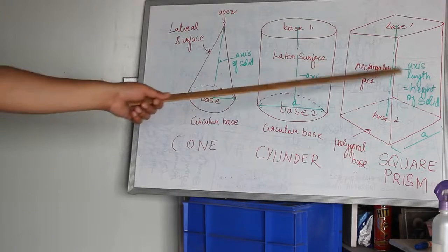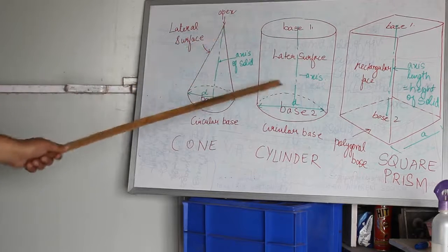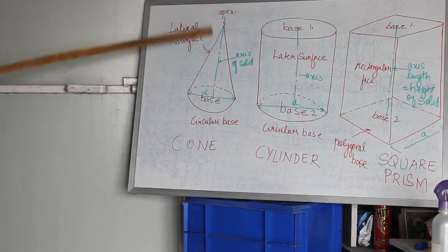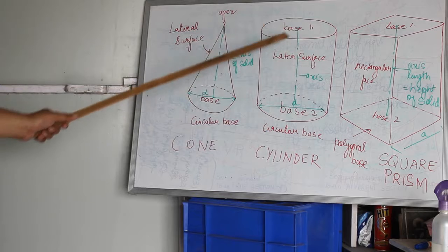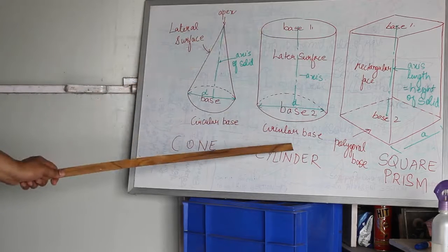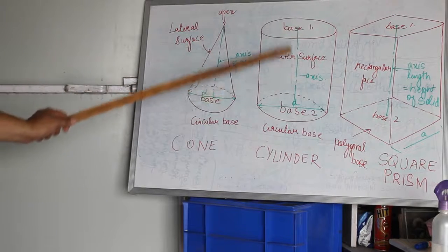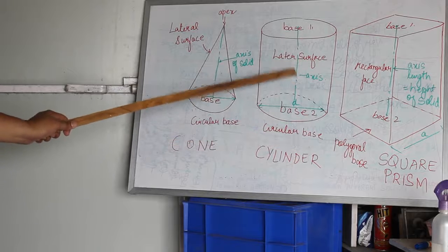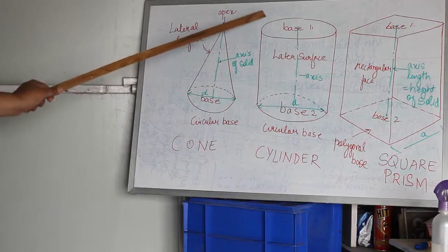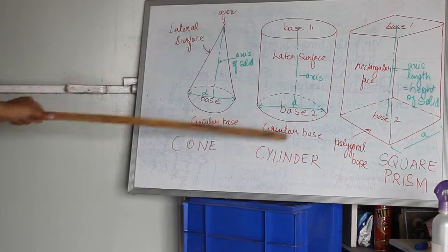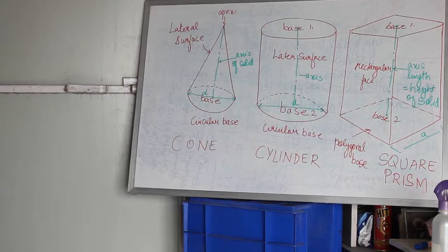So about these points, the orientation of the solid, I'll explain the orientation by using this example, which is a cylinder. I'll be making here a vertical plane and here a horizontal plane, so as to explain how the base is on HP, the solid axis is perpendicular to HP, and the solid axis is parallel to the vertical plane. Just a little pictorial presentation of how this solid orients its position with respect to the horizontal plane and the vertical plane. Let's see.